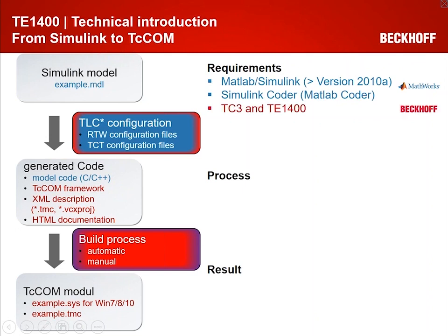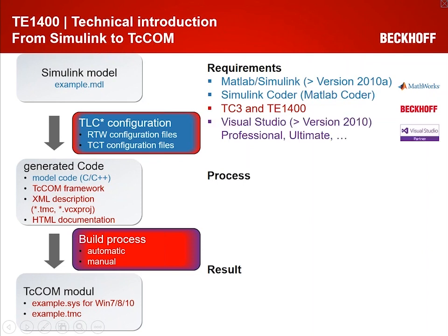Then we need TwinCAT 3, of course, and the TE1400, which is a separate setup provided by Beckhoff. And we need Visual Studio, larger than 2010, professional, ultimate, premium, whatever. The shell is not sufficient at that point.